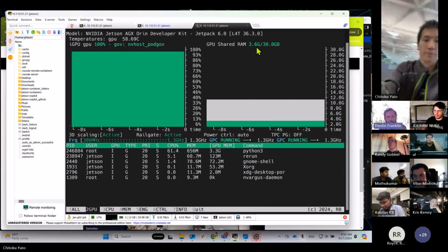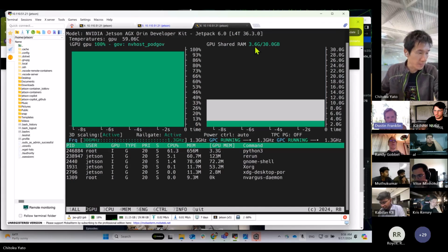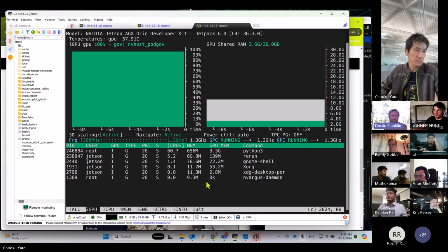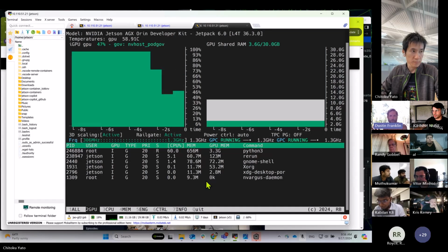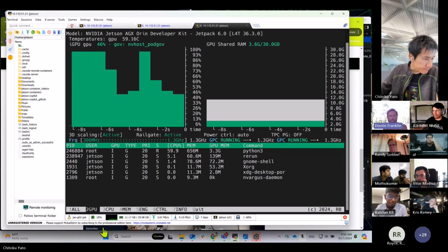You're right, because everything else is CPU, like data set stuff that can get paged out. That is something that occurred to me too, when going through this with VLA and VLM: those are all written for multi-GPU systems where there are memory transfers. PyTorch and such does not do the zero-copy CUDA managed memory, so there are extra memcopies and memory allocations on Jetson in these pipelines.